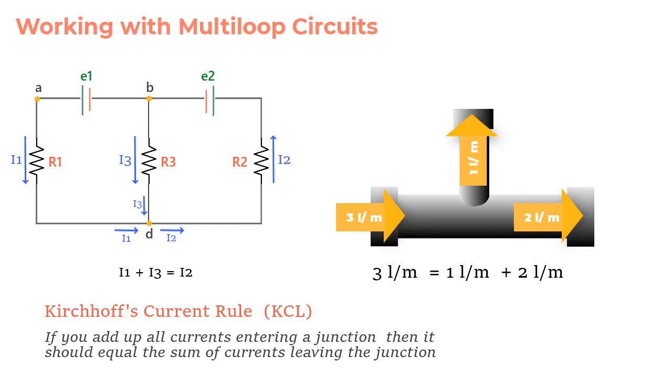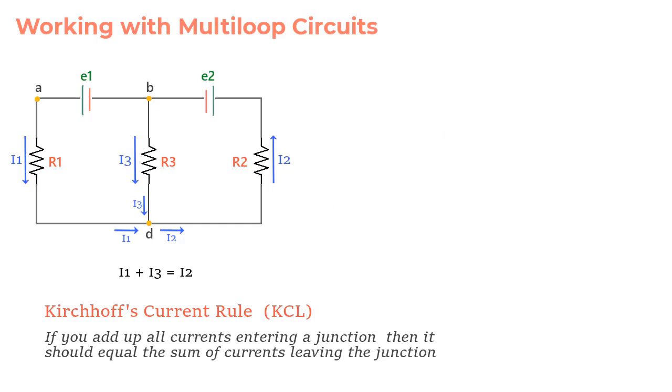So you see, we have two nice tools for solving circuit problems. One is the loop rule that we learned in the earlier lesson, and the other is the junction rule. So getting back to our problem, we see that this equation has three unknowns, and therefore we need two more equations to find the current values here.